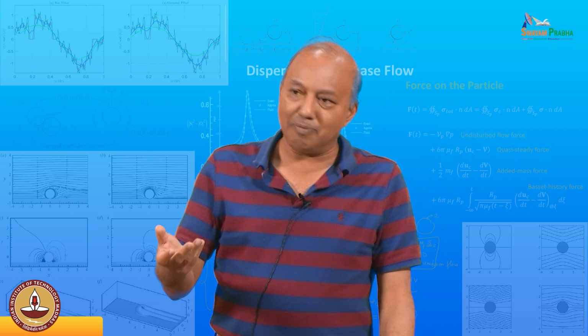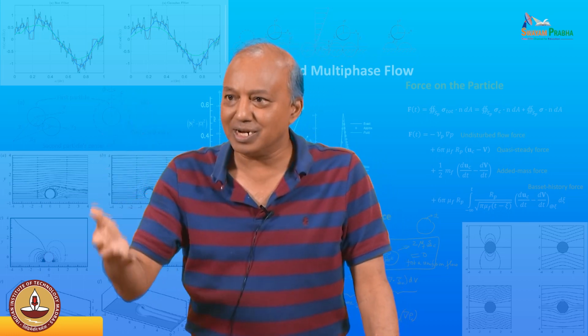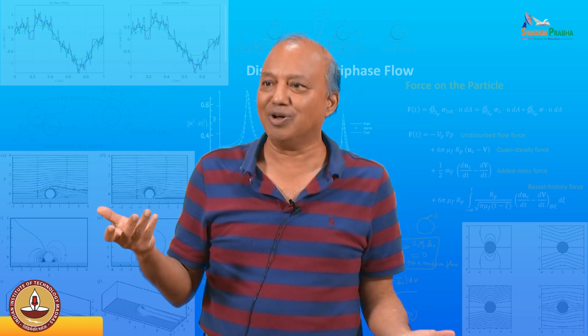But the size of the bubbles will change as per the gravity and the height. What is that? Size of the bubble will change with respect to the gravity. No, that's what I'm saying. The size of the bubble, the velocity will change, but my question is, is there relative acceleration between the particle and the surrounding fluid? If it's rising at constant velocity, there is no acceleration.